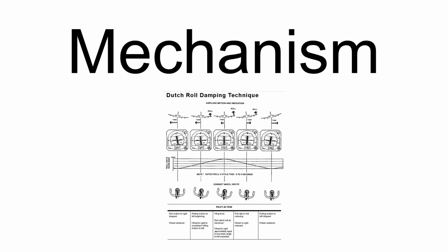The Dutch roll mode can be excited by any use of aileron or rudder, but for flight test purposes it is usually excited with a rudder singlet, short, sharp motions of the rudder to a specified angle and then back to the centered position, or doublet, a pair of such motions in opposite directions. Some larger aircraft are better excited with aileron inputs. Periods can range from a few seconds for light aircraft to a minute or more for airliners.